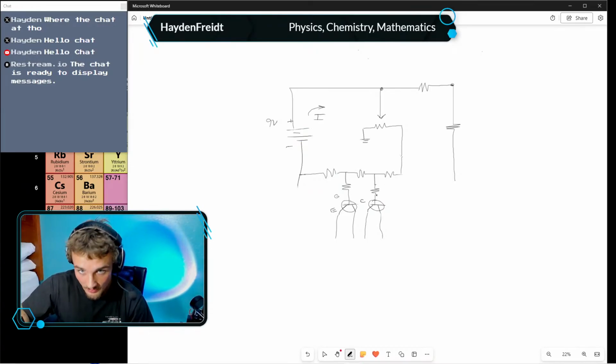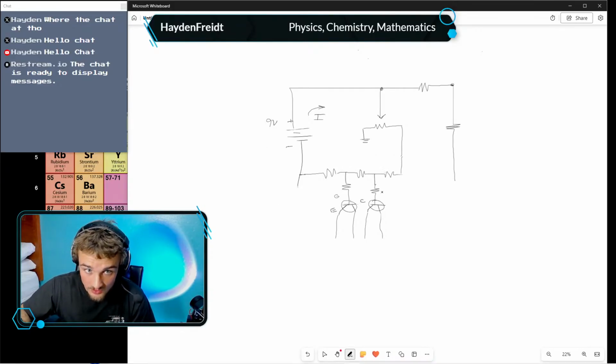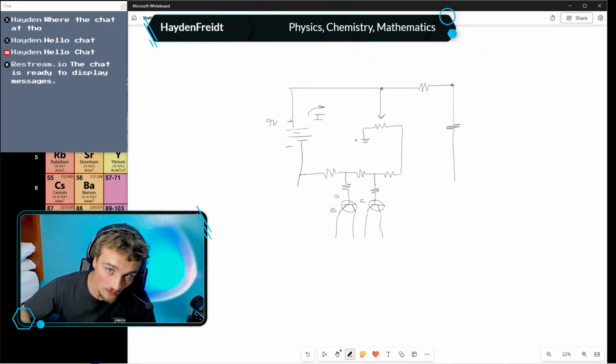The purpose of this is to be a voltage divider, a purely resistive network acting as a voltage divider. These resistors here are acting as current limiting resistors, and these are what's going to determine the current being supplied to the gates of the transistor. Because the gate itself does have resistance, but it's negligible, so all the resistance is going to be determined by these resistors here. Now, let's analyze the logic of this. As I vary the resistance at this potentiometer, it's going to vary the voltage that's supplied to this part of the network.